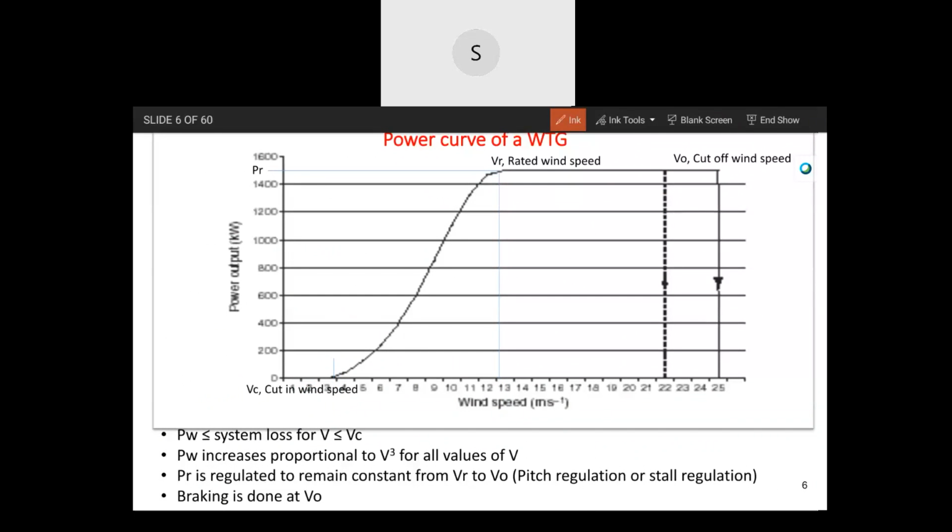No, not only that. It is taking all the pain and extracting only that constant power, keeping the generator safe. At cutoff wind speed, we are disconnecting. We are disconnecting means we are stopping the generator. Actually, that process is a 3-stepped process.